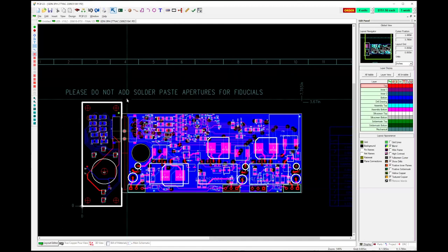We did it. It was fine. The boards came out just fine, but it's not something we actually went to production with, and it really wasn't necessary for the boards to work. Again, if you're running a lot of power, you can put heavy copper on the inner layers, but it's still going to rely on the thickness of the traces on the outer layers, so it's not always that important.